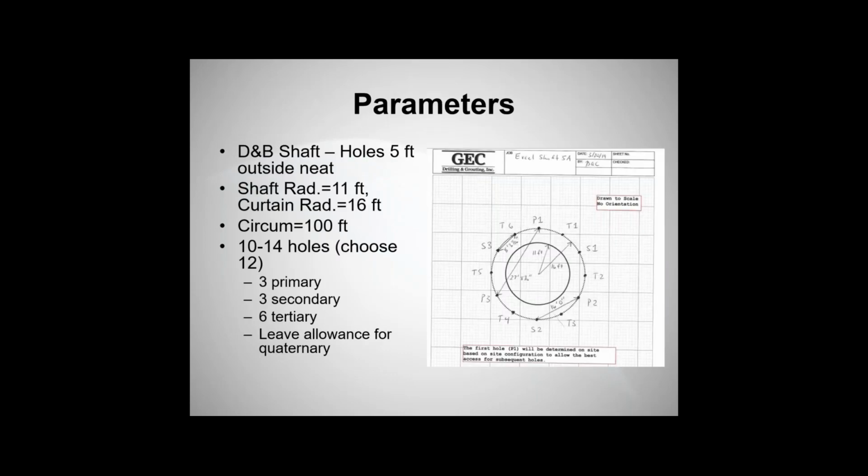It's a pretty typical project. So the method, again, because we're talking about deep rock grout curtains, then we're assuming that it's brittle deformation, consolidation grouting, so we're filling fractures. That's our assumption that we go into this design with. And in this case, the reason that we do that is because this is actually for a mine, and they provided us a borehole which confirmed typical geology for the type of ground that we're in. We had experience doing shafts in this type of ground, not exactly in this area, but with this type of ground.